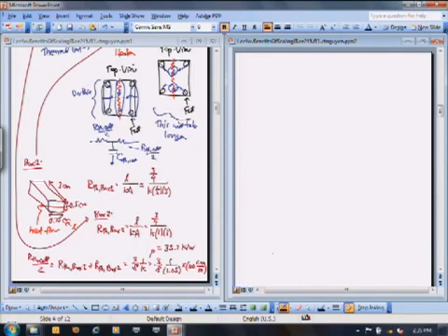So the thermal resistance of one of the feet here. And so what is the foot? The foot is really just a little cylinder. It's a short cylinder. And I don't know if I gave these dimensions before, but I'll give them now. This is 2 millimeters high. Okay, the foot, let's say, has a 2 millimeter radius. So that's the radius of a foot.